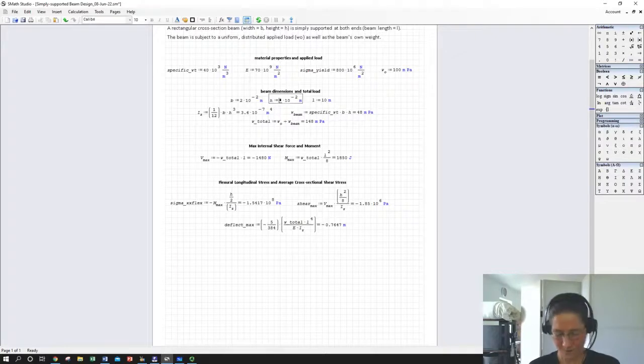So we definitely can do ourselves more good with that beam height term pretty much than anything else. And in fact, if we go up to something like 15, we can make our deflection almost inconsequential and possibly even sacrifice a little bit on width.